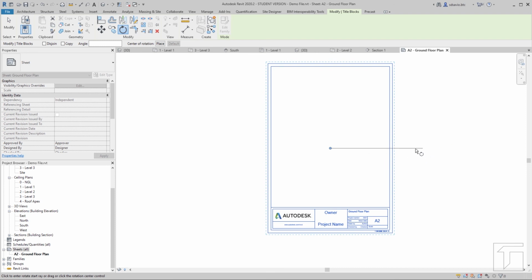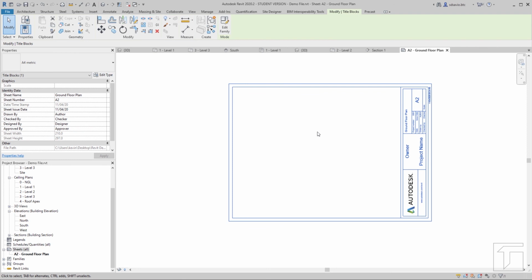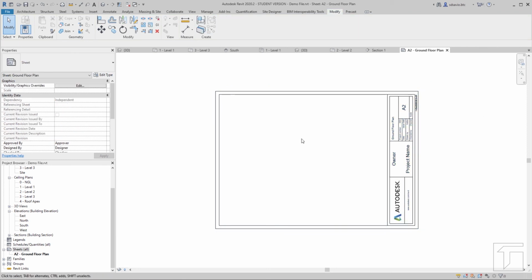Okay, so we snap on here, so Revit instantly finds the snap point. Also here it can snap by 90 degrees on the vertical axis. So I'll just snap on the horizontal, click anywhere, and this time I can now rotate counterclockwise going to the left, and then snap it on 90 degrees, and that should rotate our sheet. So now we can readily place our sheet, or rather our floor plan here.